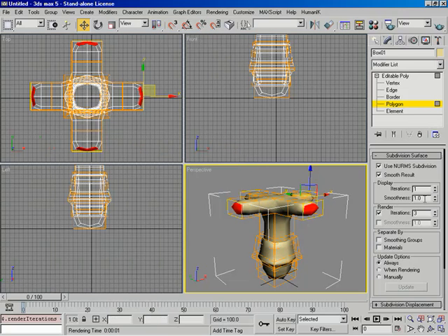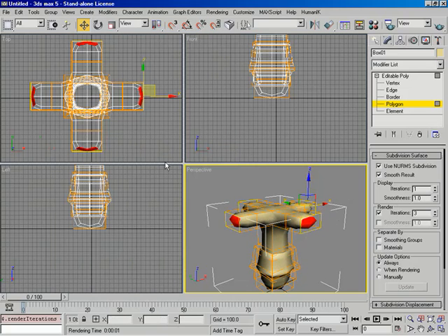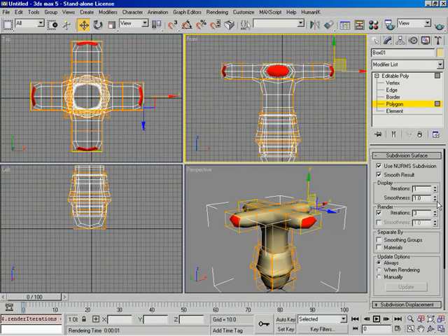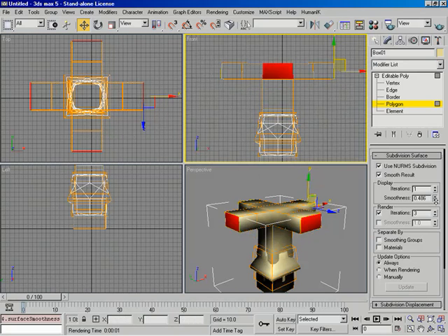So watch what happens right now if I start taking my smoothness down. It's actually going to be a little bit easier to see this up here in the front view. So we'll start turning it down, and we're going to start losing detail. Here it comes. Whoops, went a little bit too fast. We start losing more and more detail until we get a little bit too low. So there we are down at 0.5, a little bit less, 0.4, and finally we get all the way back to where smoothness is almost at 0, and we've got basically our original shape.